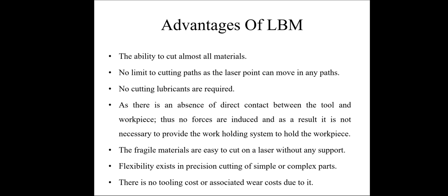It has the ability to cut almost all materials. There is no limit to the cutting path, as the laser point can move in any path. No cutting lubricants are required, as there is an absence of direct contact between the tool and workpiece. Thus no forces are induced, and as a result it is not necessary to provide a work holding system to hold the workpiece. Fragile materials are easy to cut with a laser without any support.